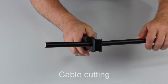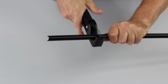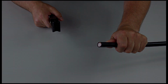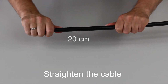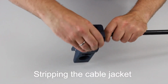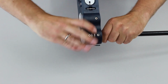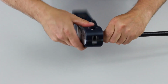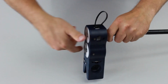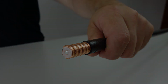Never use a saw to cut the cable. Move the cable cutter in a side-to-side motion and apply pressure to obtain a clean, smooth cut. Then straighten the cable to about 20 centimeters. Using the peeling tool on the Uniprep tool, peel off the sheath by working your way forward with a light feeding motion and turning the tool around the cable until you can see the end of the outer conductor protruding slightly. Clean off any removed sheath residues.